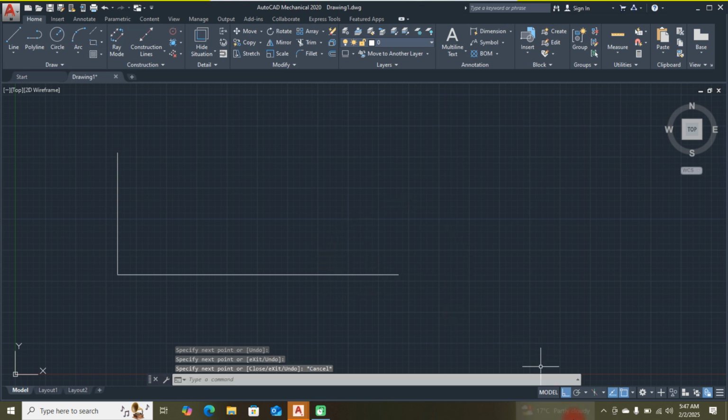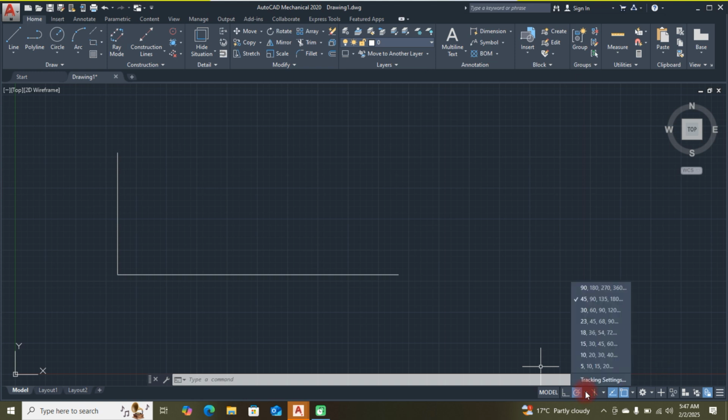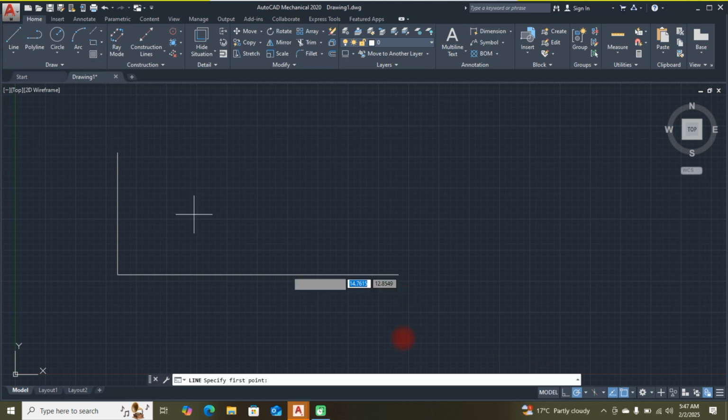Okay, so there is another line utility command which restricts you to bend that line at an angle. Besides this icon here, there is this drop down icon. As you can see, you can pick the angles you want. Like this one is for 45, 90, 135 and 180. So you can vary them according to your preference. You have chosen that.